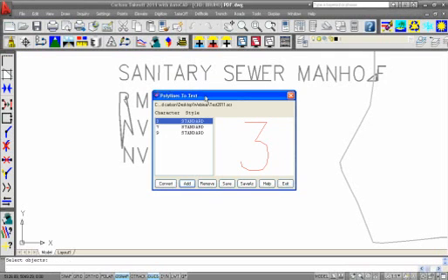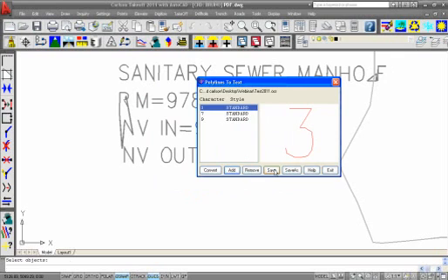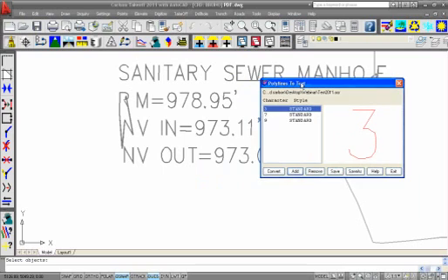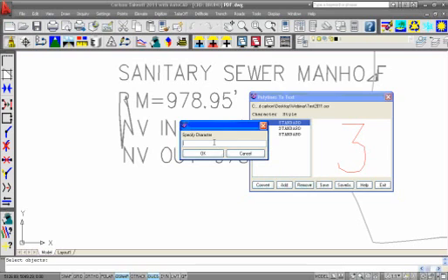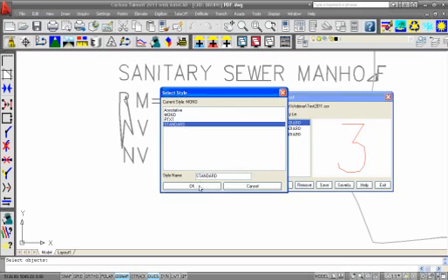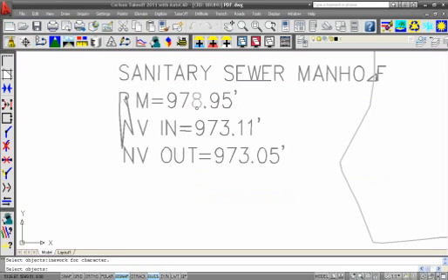Yep. So this is a library where I can save this file and load it on the next job. So this can be a one-time setup, but if you're getting different text, a different PDF, the 7s and 3s might be shaped differently. So you would need to add those to this library or a new library. Okay, and I'm going to add one more. Let's do 8. Standard, and I pick on that and enter.